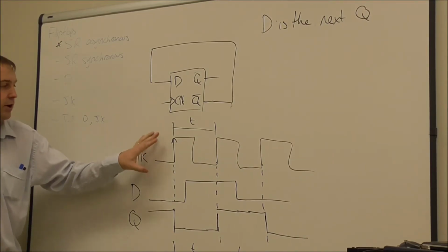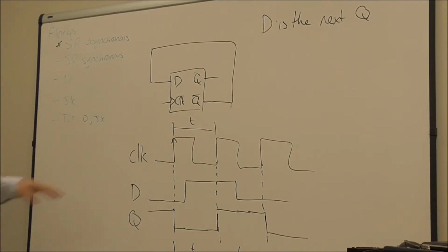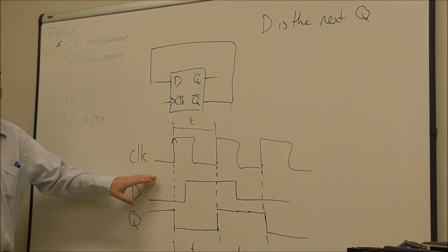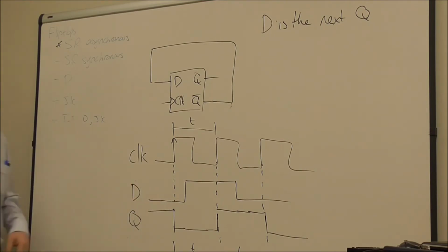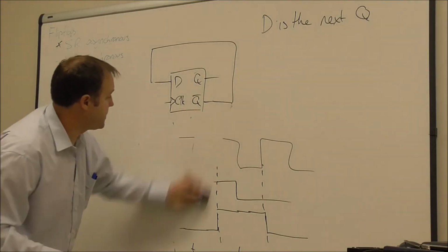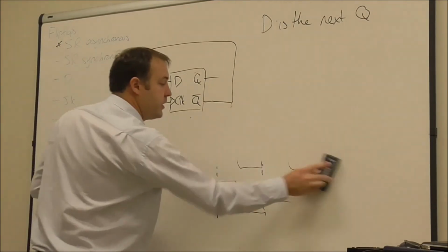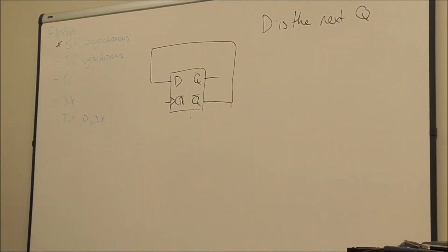Right, now I'll show you why this is useful in a later video, I think, or in a later lesson. So doubling the period or halving the frequency is very, very useful. And it's very easily done with a D-type flip-flop. All you need to do is just connect two pins together. So that's D-type flip-flops. They are a synchronous flip-flop, meaning that the outputs only change when the clock rising edge is seen, or the appropriate clock edge.